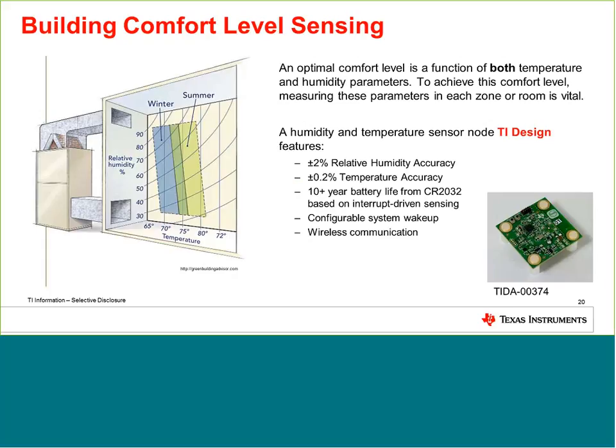So here we can see on the left side there is a zone of temperature where we are feeling very comfortable. We are feeling comfortable from 68 to 82. That's our comfort zone. And also the humidity can go from 30% to maybe 80%. Now, we also have two different requirements, depending on the winter and the summer. In the winter, our comfort zone will be at lower temperature, while in the summer we need to have a little higher temperature.